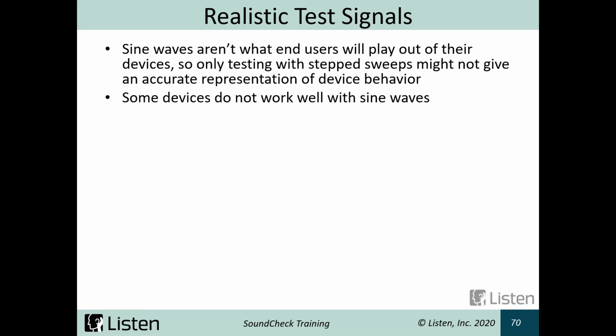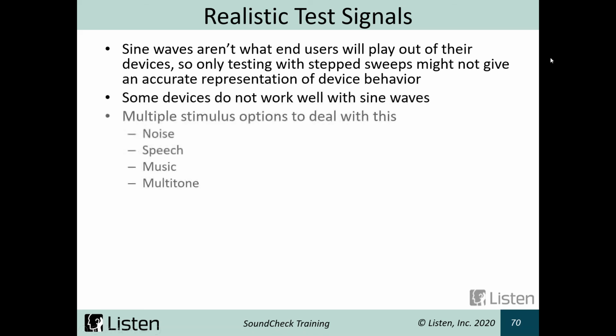That's great when you're using the device for its intended purpose, but if you're trying to test it, you might not be able to get accurate information with the sine wave. Noise cancellation, compressors and hearing aids, different types of muting circuits, these all make it difficult to test finished devices and use sine waves to get really accurate results for how they're actually going to be used.